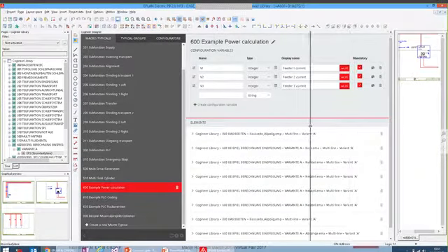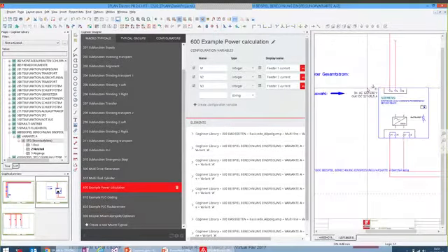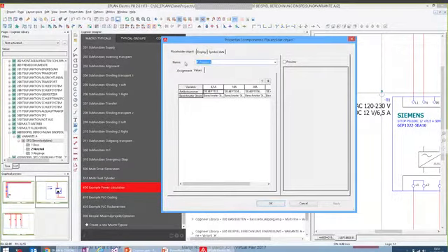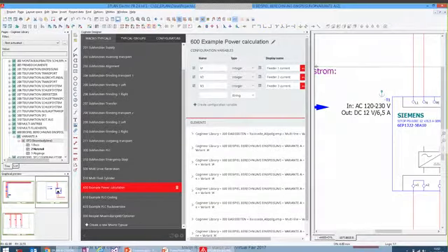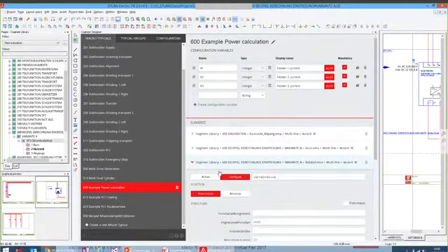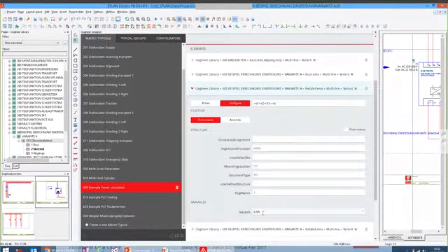So let's first have a look to our macro and let's see here. And this macro has a placeholder, like you perhaps know. And in this placeholder, the placeholder has a name. This is the name of it. And we can control the different value sets in this placeholder. So we can say in this macro, which is controlling the supply, we can have here the summation of the 3 variables. So we can say, okay, if V1 plus V2 plus V3 is lower or equal than 6, we will generate our macro with the selection of 6.5 amps.